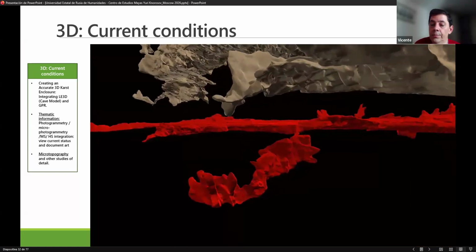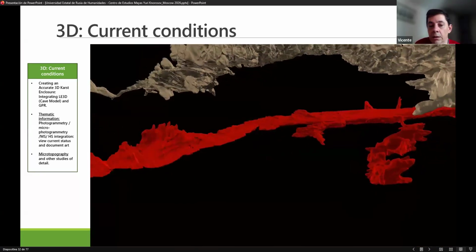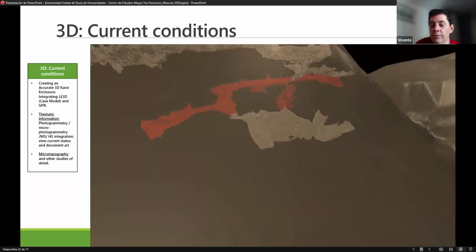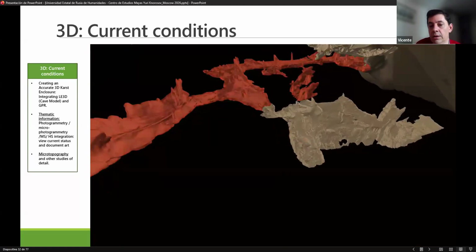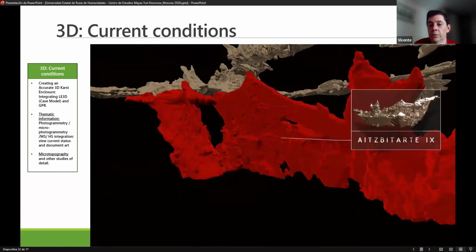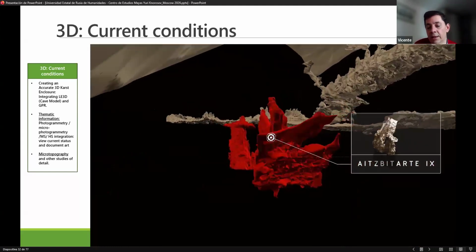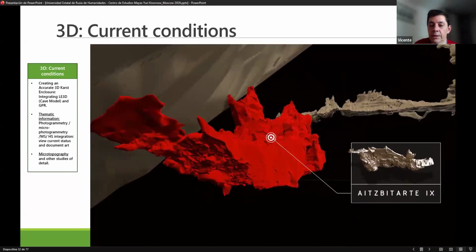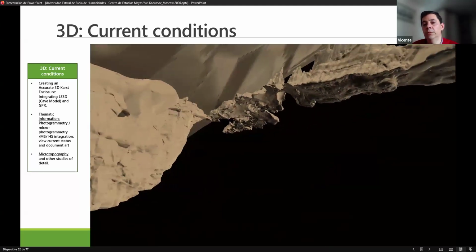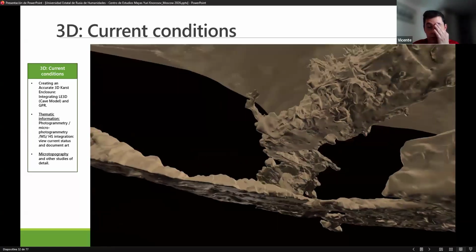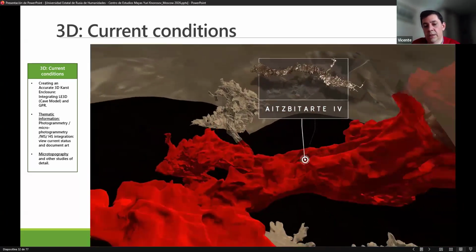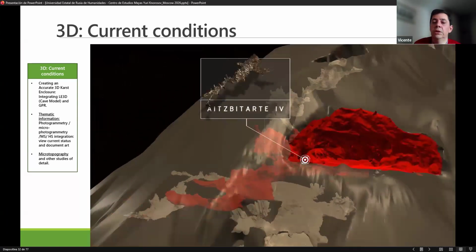These models are created by laser scanner, but you can also create this model with photogrammetry. What is the advantage of the photogrammetry? That you have texture and, if you calibrate color, you have color calibrated and you can compare what you have in front. Here you have only geometry and a digital number of the laser scanner that, depending on the wavelength, usually is lost. Okay, you keep it in point clouds but not in models because it's useless. Okay, you could use it, but it's not common to keep it.